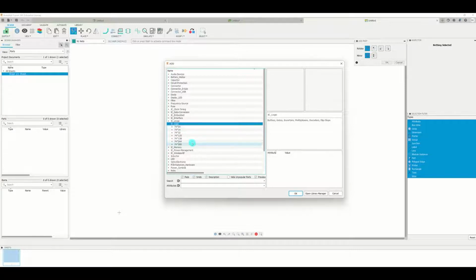Okay, so for example, that's a 244. Later on, we can add components to this. If we look into the library, using the Open Library Manager, we can add more components to this one. So right now, these are the default components which are being used, but if you go to the Open Library Manager, you can add other components or other libraries which are not yet used. So for now, let's just use the one here, the 244.